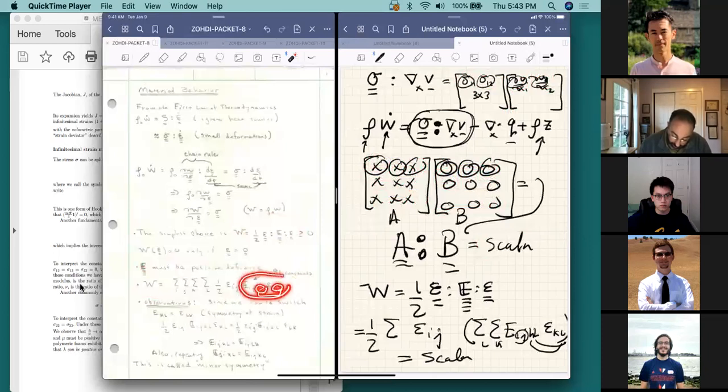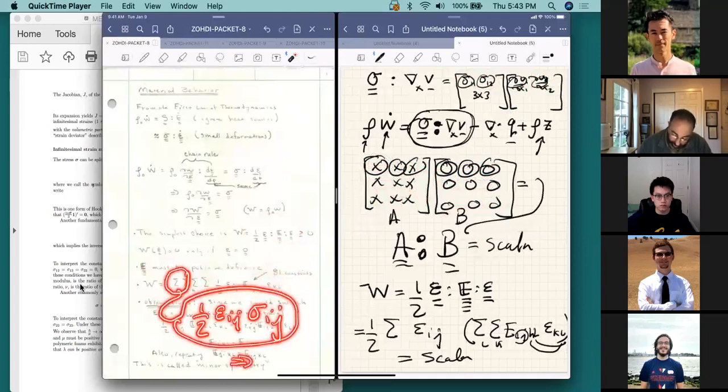So that's the first entries that are associated with those summations. And then the product of all of that stuff is none other than the stress, which is sigma ij. So sigma ij multiplied times epsilon ij, let me write that out. Epsilon ij, sigma ij is taken care of by the last 2 summations that are here. And you end up getting a scalar which has no direction or anything and no free indices.